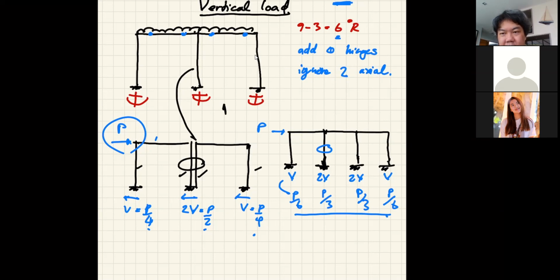We simply ignore the stiffness for the time being because this is an approximation, like I have stated before, used either to check the preliminary design, to decide how many columns you're going to have and so on, or to check the complex calculation.